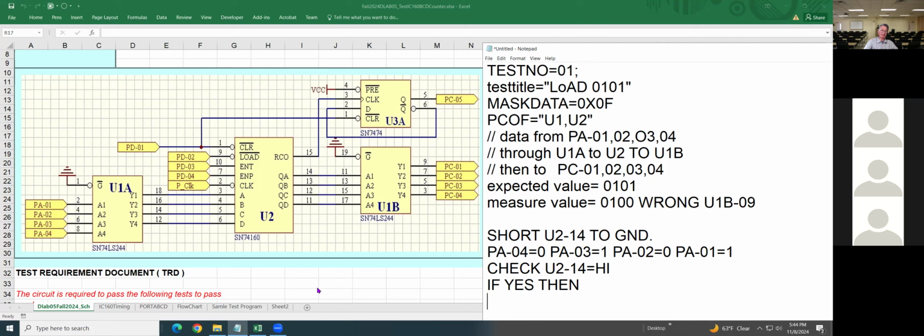That's why I bring it up a different way. Troubleshooting, instead, you go from input to the output, or the output back to the input. Now I go into the middle. If you check pin 11, you get high, okay?